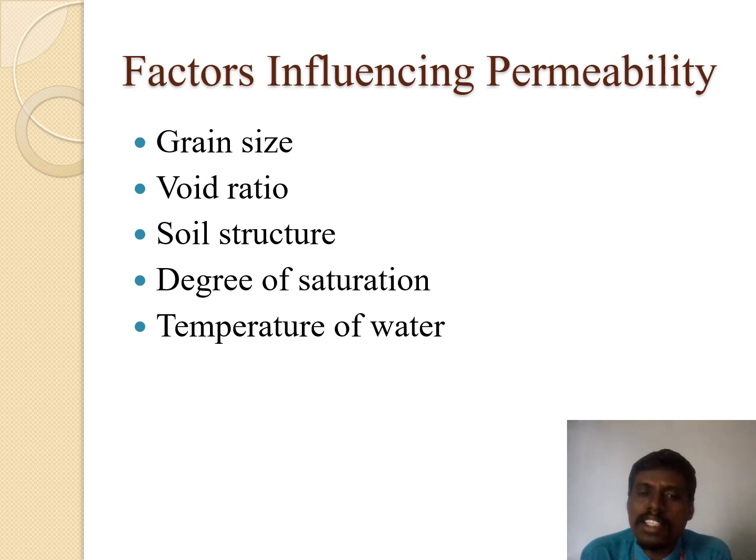If the degree of saturation is minimum, the water easily percolates into the soil and the permeability will be higher. The next thing is the temperature of water. If the temperature of water is high, the density will be low, so the water will percolate easily. Otherwise, if the temperature is low, the density will be high, so because of the density of water, the percolation will also be less.